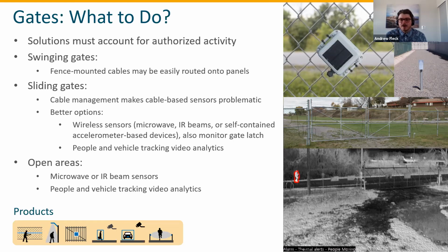Fence cable is not designed to be recoiled. There's a center conductor in it and they break. That's the reality. It's not designed to be retracted. So then how do we look at a sliding gate? Cable management becomes the biggest factor because we still have to continue cable underneath our gate. This is normally for a power aspect or potentially the continuation of the sensor cable.